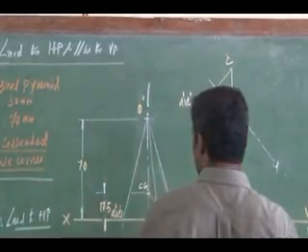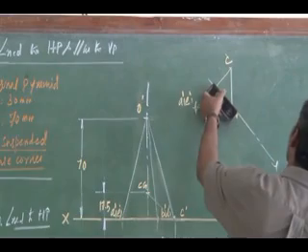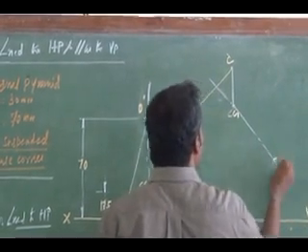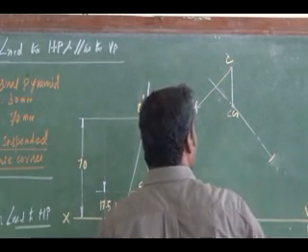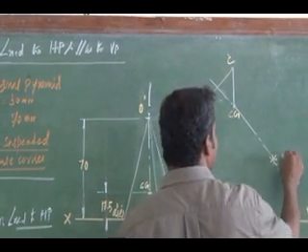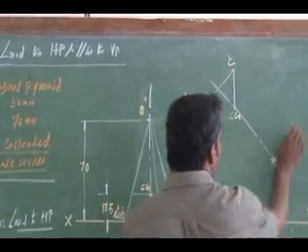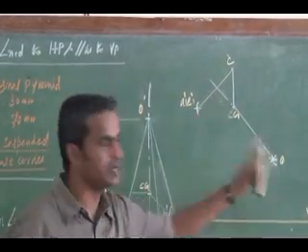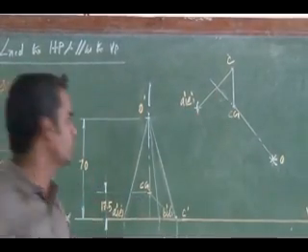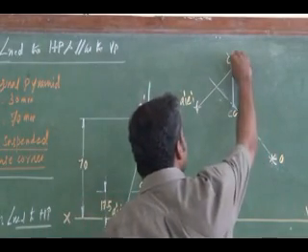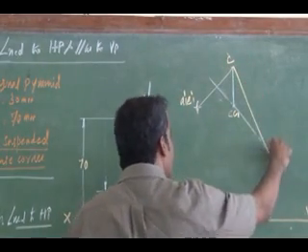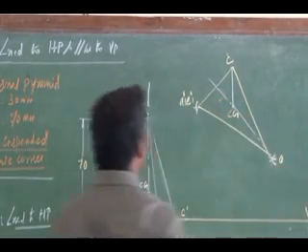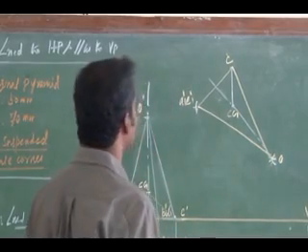Now the height: either by intersection I can assign this location as the apex, or by drawing an axis from this base I can measure the height. Anything you can proceed with. Then I can redraw this front view like this. This is going to be my front view.